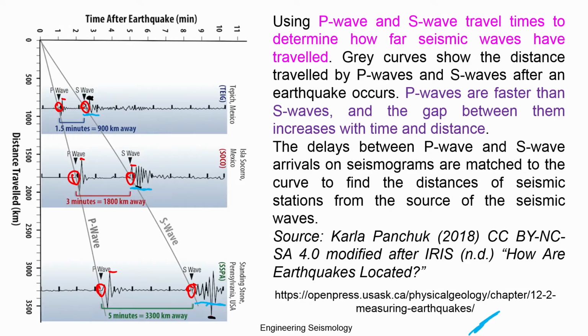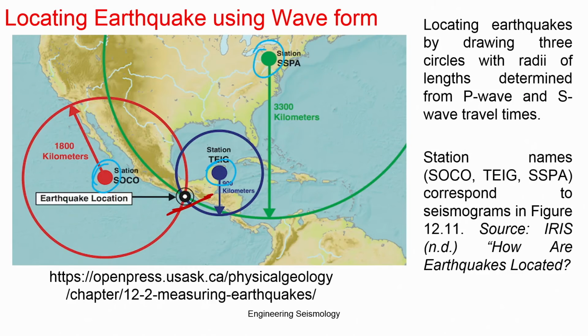Physically, the velocity in the region, like P wave velocity and S wave velocity, we have shown the range. Generally, if you have data recorded like this for a known distance in the region, then you can estimate the average P wave velocity and average S wave velocity you can use for this kind of calculation. For example, this station and this station are far apart, so the velocity in between will be different. This will be your Vp and Vs. Similarly, this velocity may be different, it need not necessarily be the same, you have to find that out.